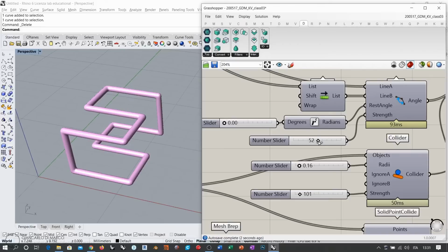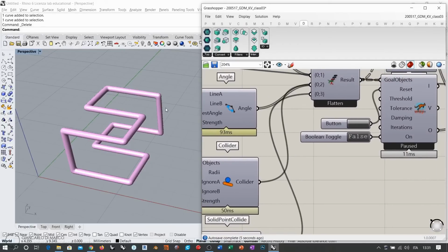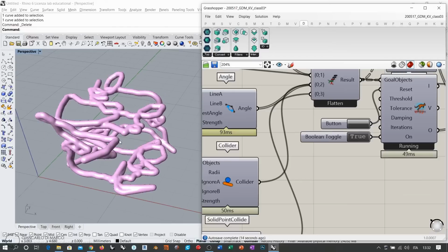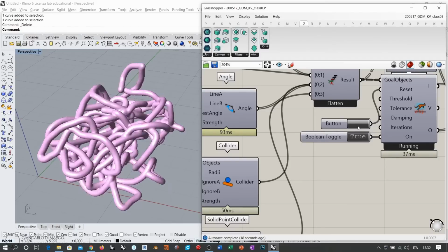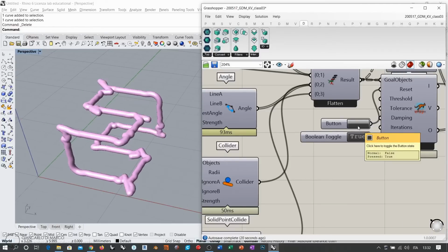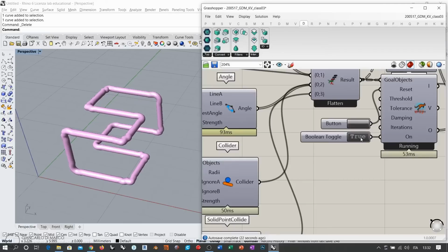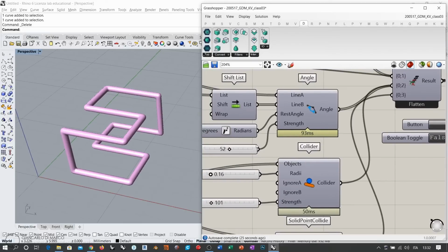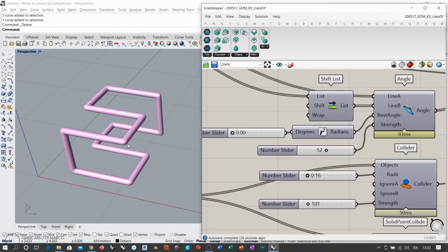Yeah, you take a look. This is interesting because this line is actually made up of straight portions, and then suddenly you have these 90-degree angles, right? So if you run the simulation, you would see that things start to go extremely bad in the vertices of this polyline. You see how the deformation starts to expand from the vertices. This is because of this angle here. So this angle is actually trying to smoothen these vertices at first, and so all the deformation propagates from these areas. And it's also very strong.